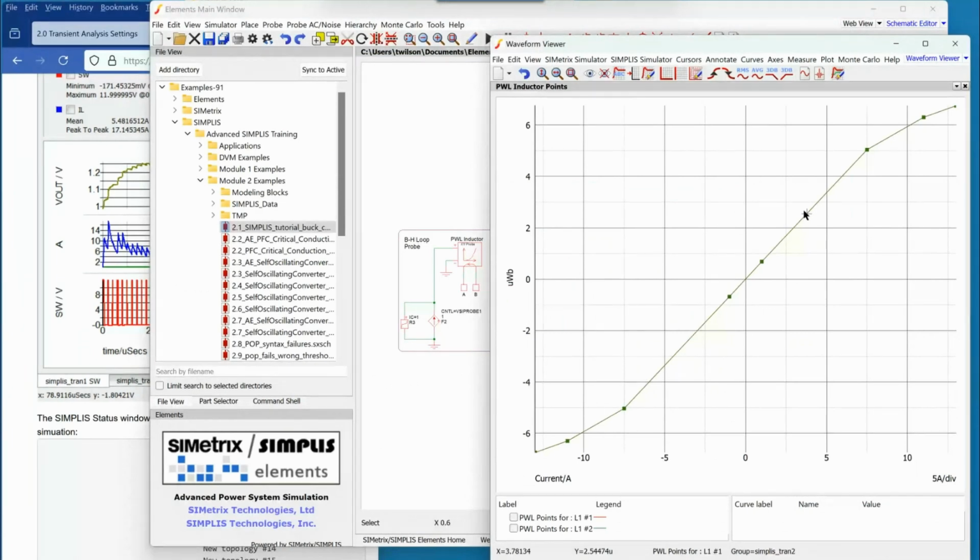I don't want to compromise accuracy, but what you'll find, let's say with a Bode plot, is that if you're going to operate up at 10 amps, you need to model this. This segment needs to be in play because this inductance is a lot different than this. And you'll see that in the AC analysis.